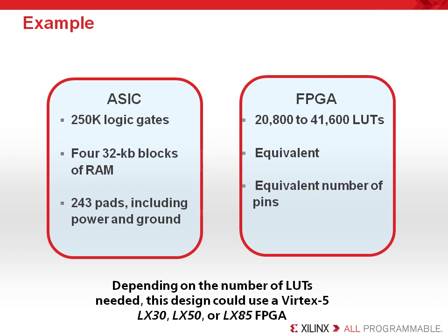So given the 250,000 gate count, let's just assume the logic maps only to LUTs and that we'll ignore registers. This design would require between 20,000 and 40,000 LUTs, so you go to the datasheet for any of our devices and look for one that has enough LUTs, RAM, and I/O pins. In our case, we'll assume the design needs to target Virtex-5, and after referring to the datasheet, we found that we can choose from a number of densities. To narrow the choices down, we would probably recommend that the designers synthesize for each of these devices and choose the one that fits most efficiently.